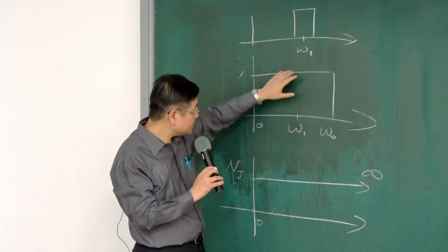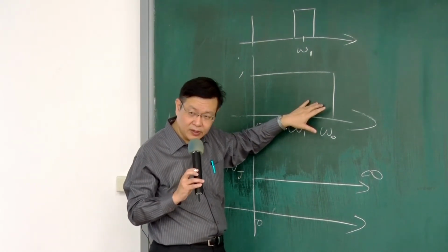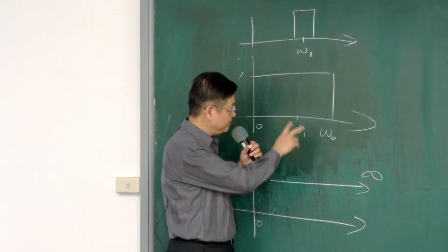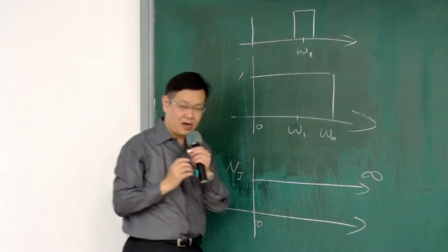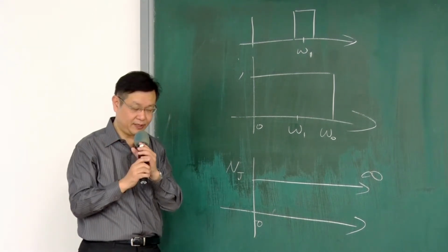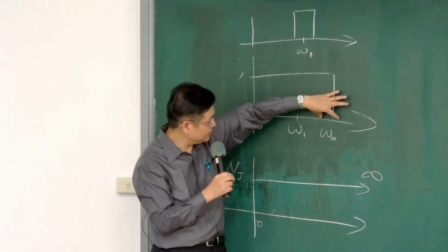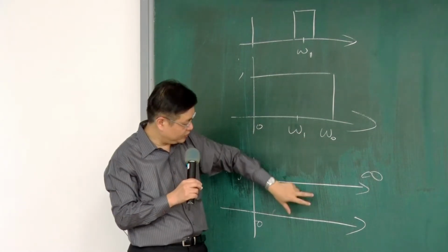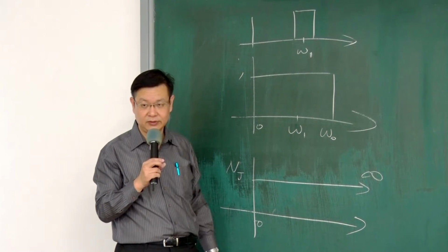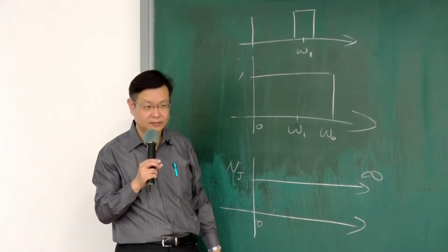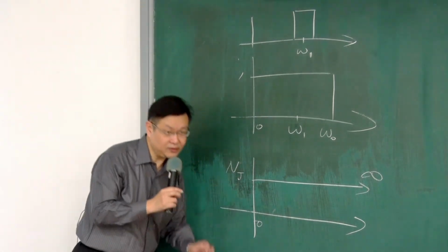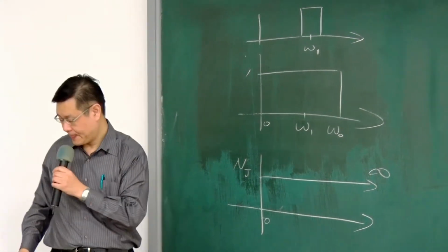So that's why when you're operating a gyroscope, we take the signal only at that natural frequency part, so maybe we can consider just fixing our information. The input information, getting the information only in this small region, in order to reduce a lot of noise going into the signal channel of the system. It's a little bit difficult to understand, but when you do the real design, you will get some idea about the situation.